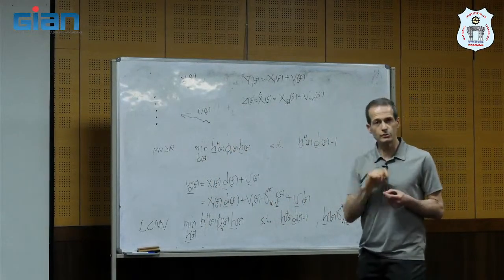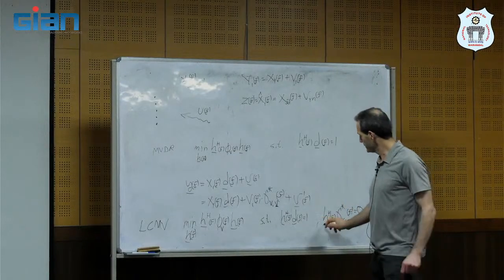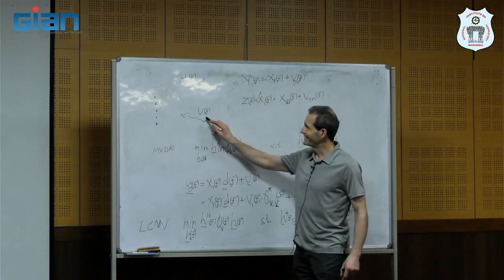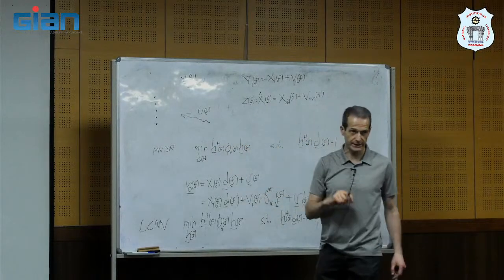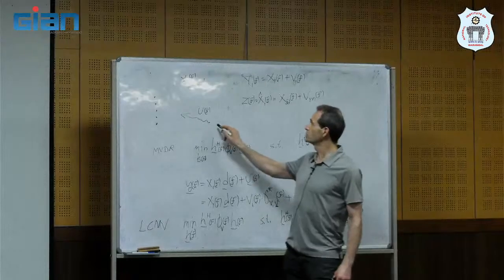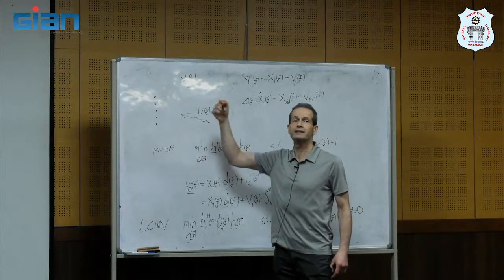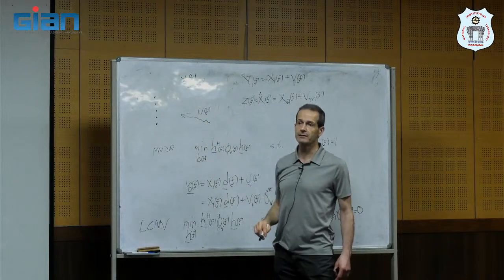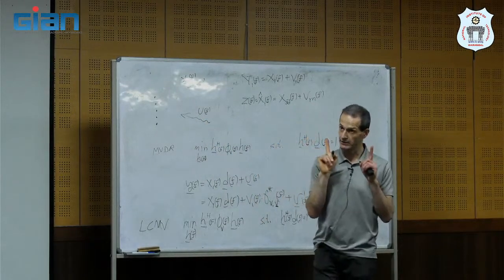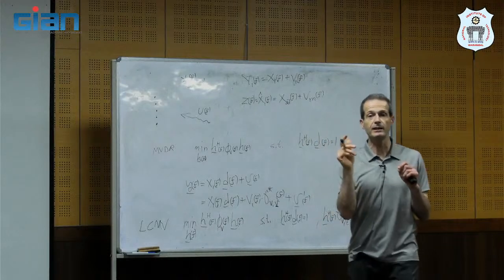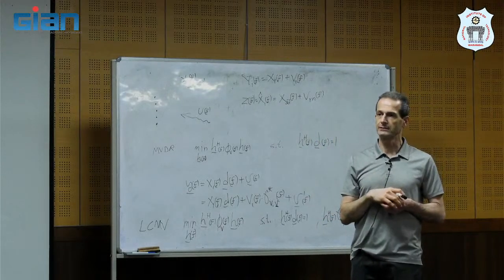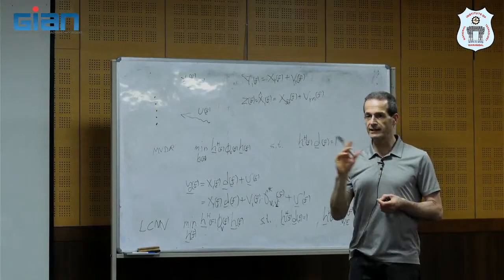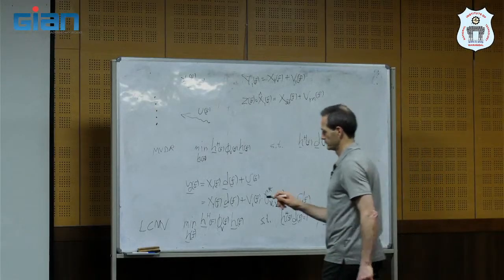So what do we need to do? Is to put here another constraint that even though this has low energy, we want to suppress the contribution of this noise source because it's very disturbing. Not because of the energy, because it's disturbing, for example, if it's non-stationary. Okay? So this is the advantage of using LCMV.